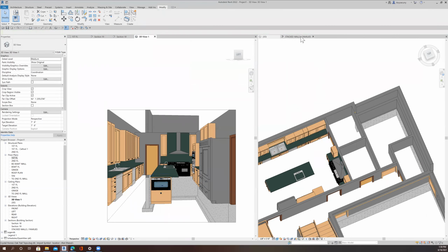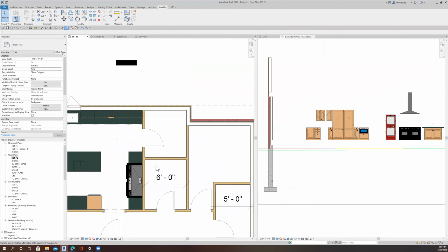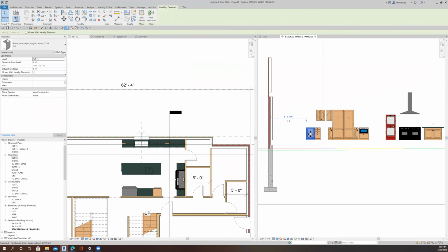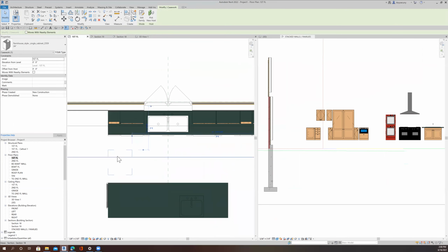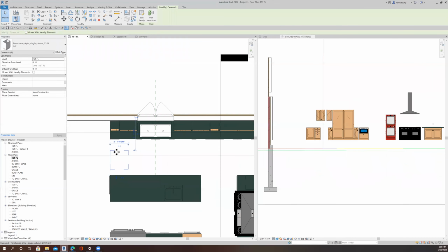So here's my stacked wall family. And in this view, I'm going to let this be the overhang. So let's just grab this guy and create some more. And I'll just put him over here. And let's click on it to see. I want to see where the arrows are, so I know which is the. Let's see the arrows. So let's drag them down to here.